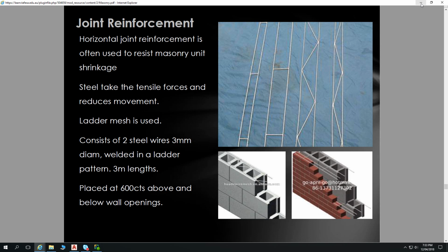Alright. So moving on from bricks to talk a little bit more about concrete blocks. With our slab, I was talking about control joints earlier on. We want to put cuts in there to control that shrinkage of the concrete as it hardens. We also want to do the same with concrete masonry walls. And I did mention earlier as well with bricks, the shrinkage of a mortar gap works well with the expansion of the clay brick in that wall when it's freshly laid.